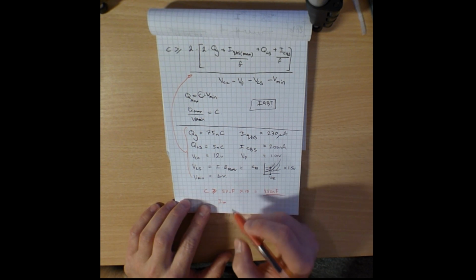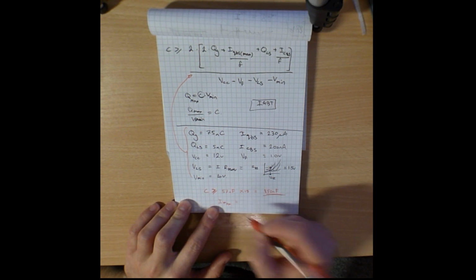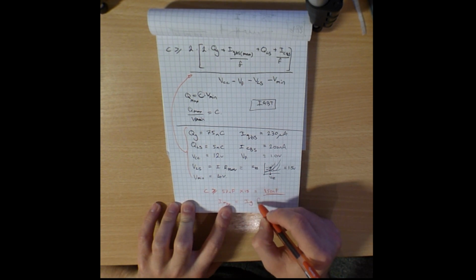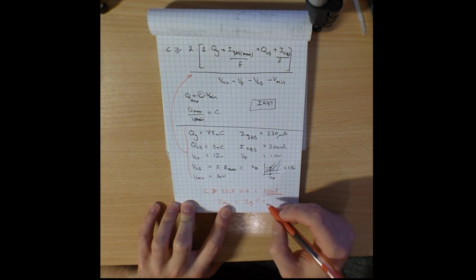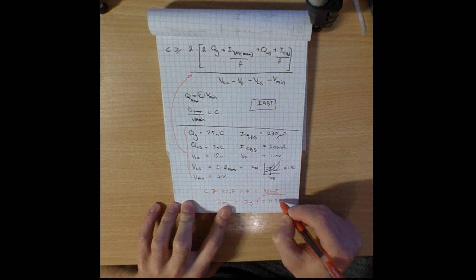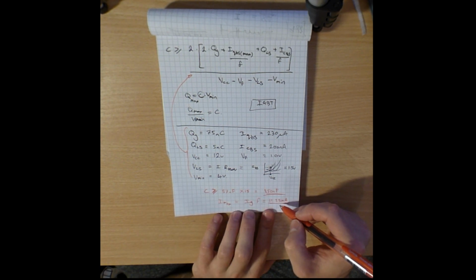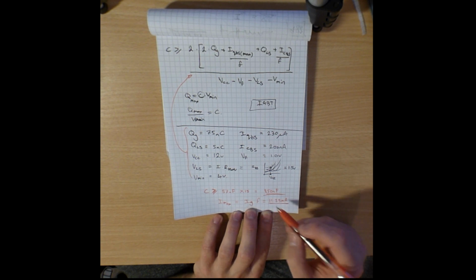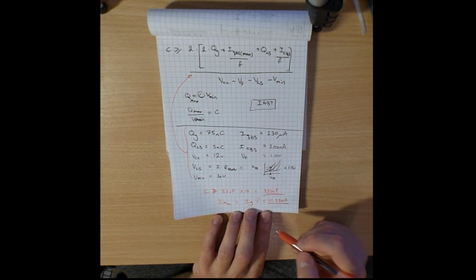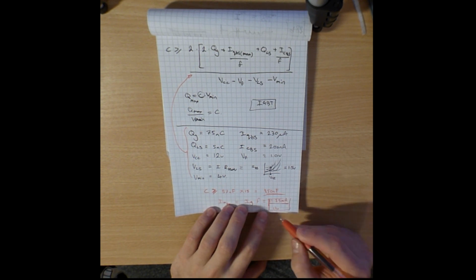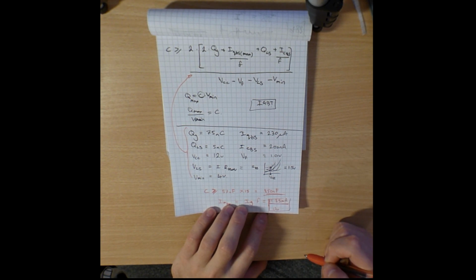And now we can look at the current rating of the diode. That's the gate capacitance, or total gate charge, times the frequency. And in my case, that's a total of 11.25 milliamps. So I need to make sure that my diode is capable of passing 11.25 milliamps, and also that it's able to block VCC, which it will be, because my VCC is about 12 volts, and most diodes are going to be able to block 12 volts at 11.25 milliamps.